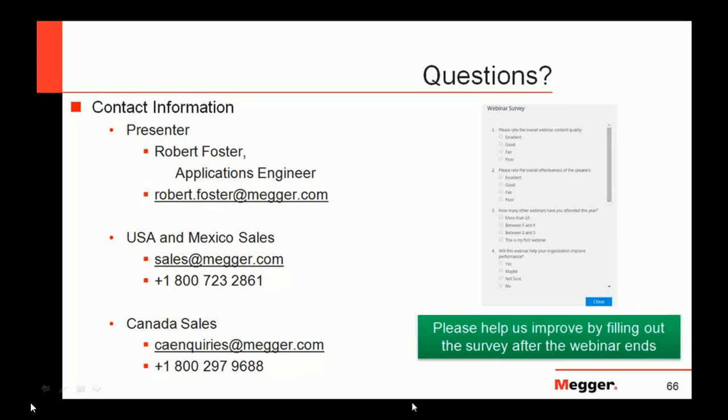And I always feel like manufacturers act like their breakers don't need to be tested at all. And of course, we make test equipment, and I was a field service engineer, so I believe testing is very important. But I would say it's still important, especially if you have circuit breakers that you've had failures on. There might be things you can pick up with travel that you won't see just in timing.